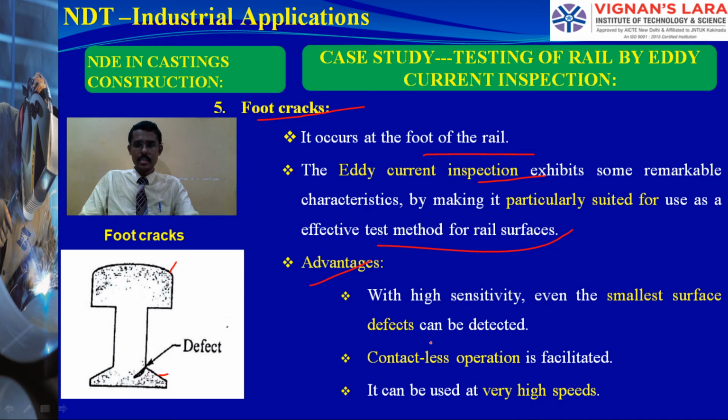Advantages: with high sensitivity, even the smallest surface defects can be detected. Yes, a contactless operation can be done. Yes, it can be used at very high speed. Definitely, eddy current testing makes this possible.